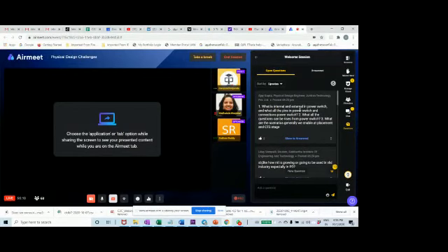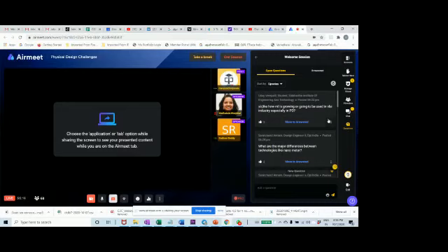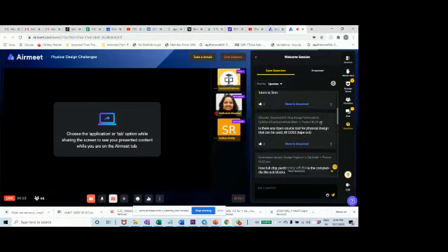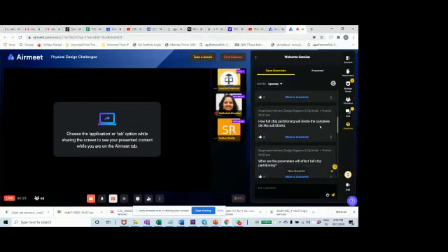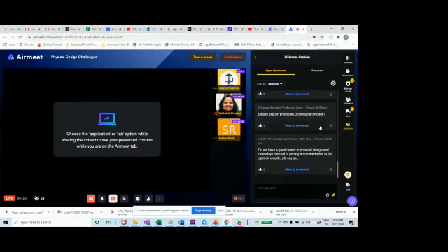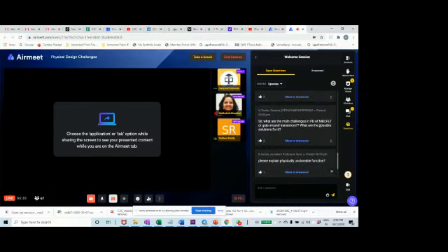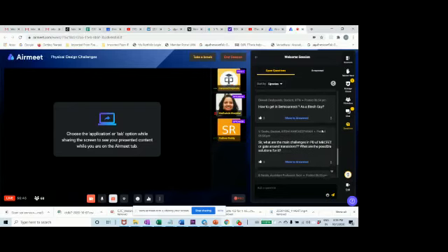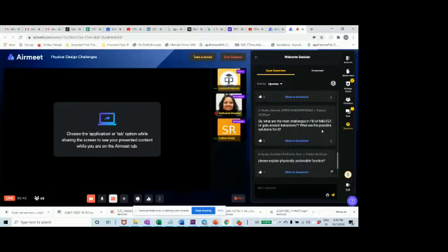If you are going for a design with power switches, you have to decide first what your power switching strategy is. It can be distributed power switching or a power ring kind of structure. If you are making a specific ring around a network and you want to switch that off, that is one method of switching. Or you have distributed switches which are like logic gates placed across the design, and those can be switched with a sleep signal that your functionality will decide when they have to be switched off. If you are using distributed power switching, yes, during placement you have to take care of that.